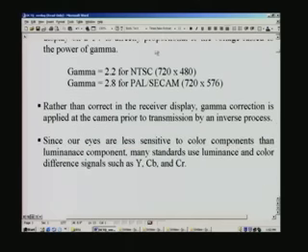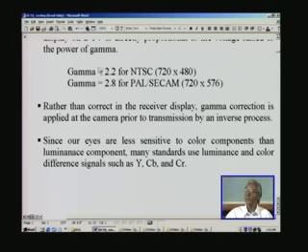So, here we say that we need to incorporate gamma correction. If we were to do it at the receiving end, we have a TV at every home, and there will be innumerable ones. So a better way to save the cost for the consumer will be to take the complexity right to the camera end. The inverse of this, a factor of 0.45, will come: V to the power of 0.45 will be the intensity which needs to be corrected at the camera end before transmission. That is what is mentioned here.